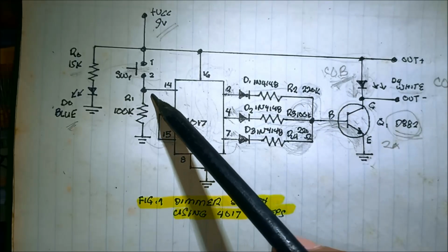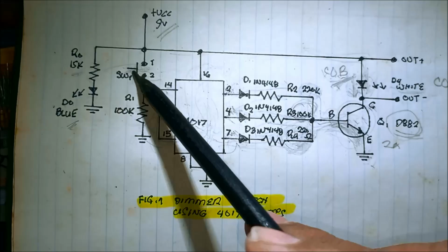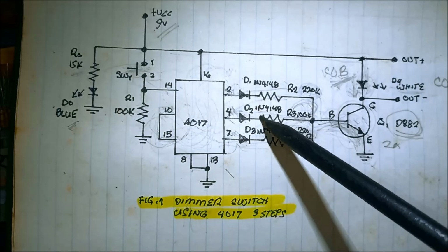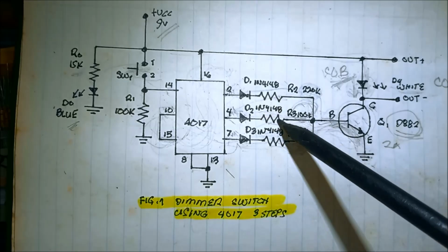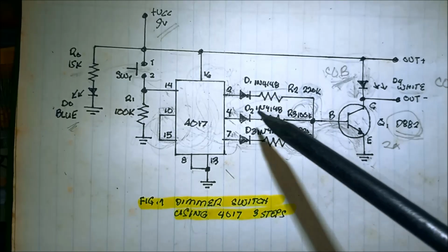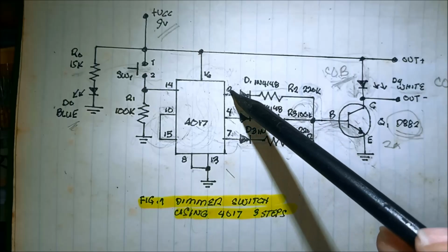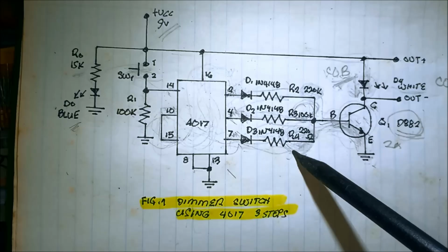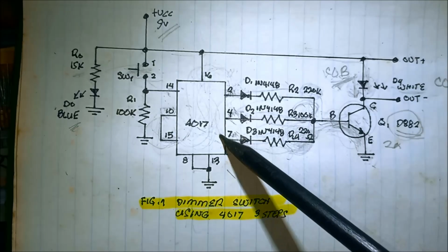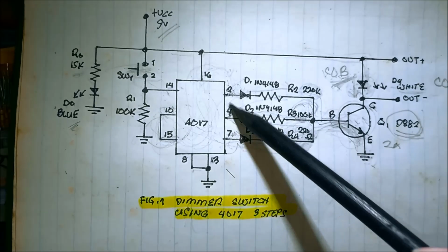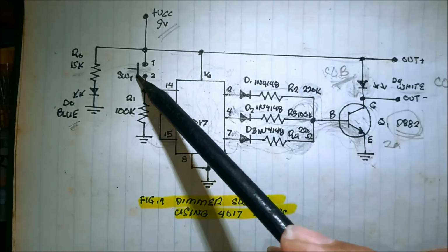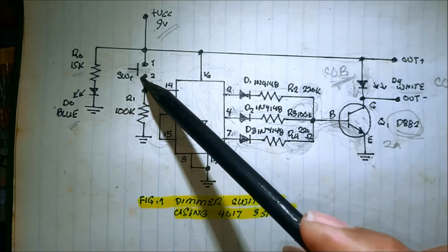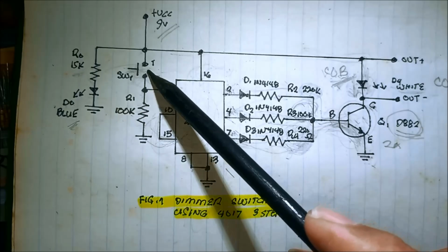The only error, there is an error, is due to the switch bouncing. Whenever we press it, sometimes it toggles faster. Okay? Sometimes it skips pin number 4 and goes to the bright light, or dim light and then to the bright light, skipping pin number 4. So that is some problem that occurs here due to the switch bouncing.